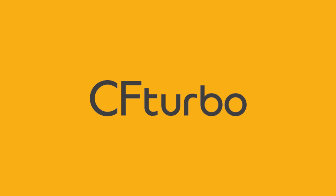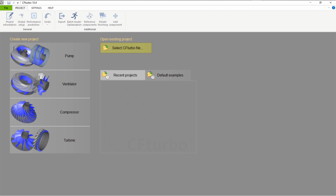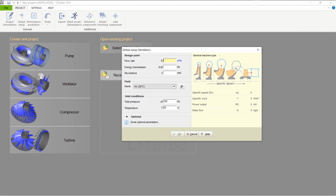In this video, we'll be demonstrating the aerodynamic design of an axial, low-pressure fan, including a CFD simulation. First, you create a new project choosing the ventilator design module. Insert the design point of the fan. The design point is defined by volume flow rate, total pressure rise, and rotational speed.